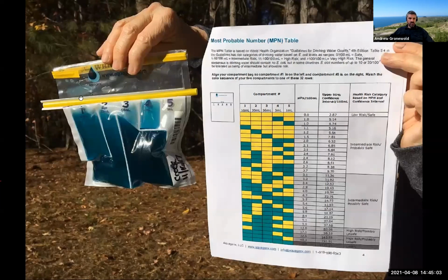And what we were able to do is design this testing kit to have 1, 2, 3, 4, 5 different compartments, each of a different volume. And with this test kit, someone can take a water quality sample, divide it up among these different pouches, and read the pattern of positive and negative bags in each one of these pouches. And then using a statistical model, we can develop a table like this one that tells us for any pattern of positive and negative bags, what the risk for water quality borne contamination is and threats to human health.